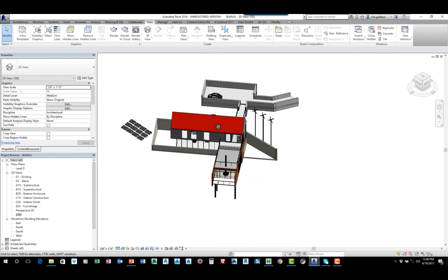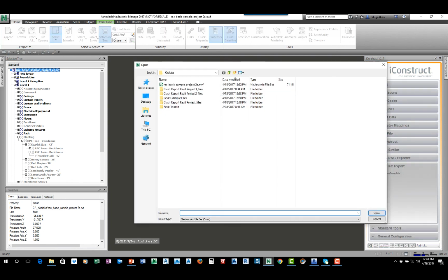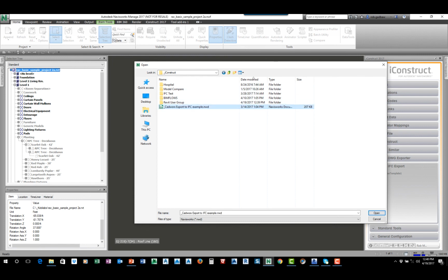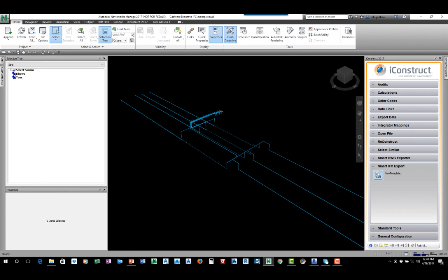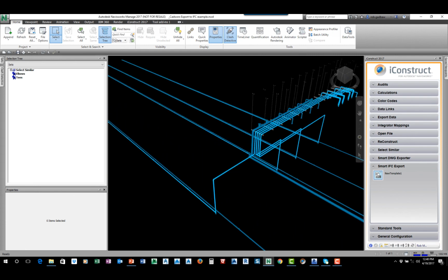Okay, so one other thing on the IFC here is I'm going to show you how to map it. So if you really want these properties, if it's a pipe, I want it to be a pipe in Revit. Okay. In order to do that, you need to map it. So let me just back out of this, and I'll just show you this. So let's grab in here NWD. This is a model out of CADWorks. Okay, so this just got a whole bunch of pipes and elbows and fittings, stuff like that. So I want to take that so I can take it into Revit, but I also want things to be mapped. Pipes to know they're a pipe, elbows to elbows.